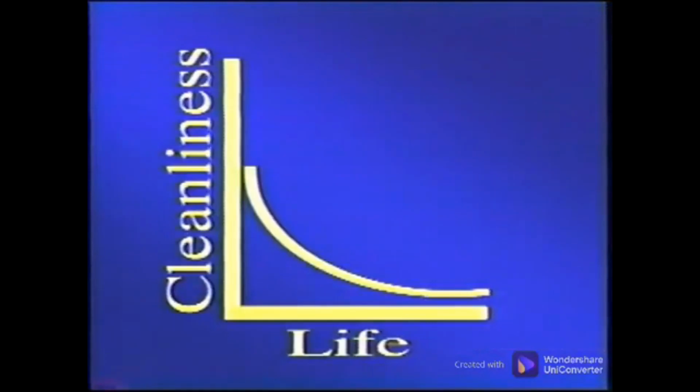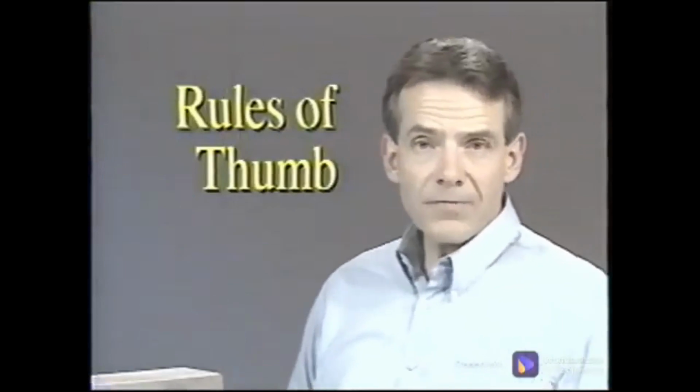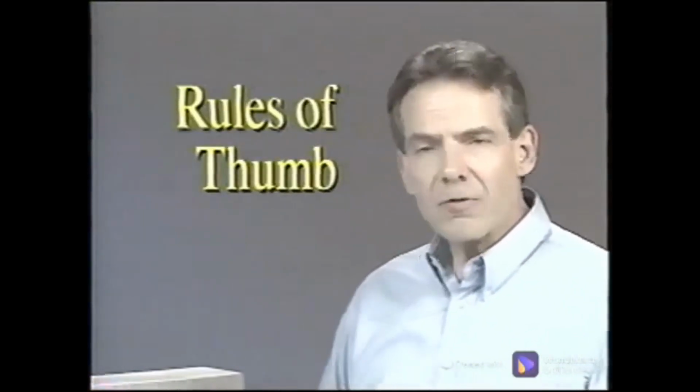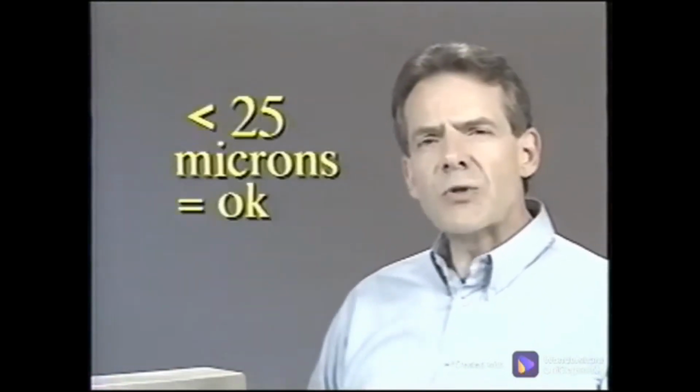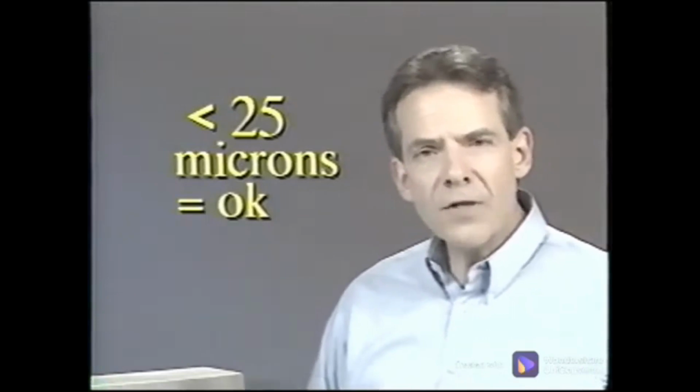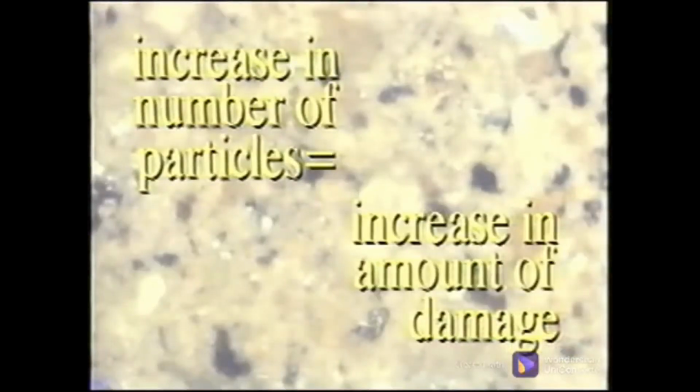Studies show that the cleaner the oil, the longer the machinery will last. Therefore, it is important to continually increase the cleanliness levels of critical equipment. A typical sample may have many particles in the 2 to 10 micron range and not be abnormal. There are 3 rules of thumb concerning particle contamination. First, for most mechanical systems, clean operations, if particles are less than 25 microns, the equipment is generally operating satisfactorily. Secondly, the larger the particle, the greater the damage, and an increase in the number of particles indicates an increase in the amount of damage.